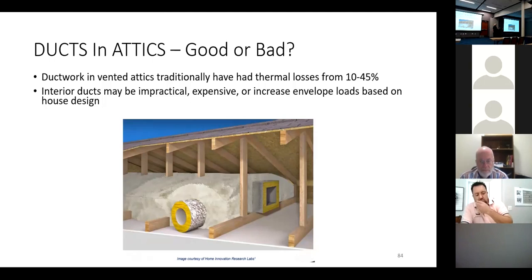So by amendment, the leakage rate right now is ridiculously high. You can leak 6 CFM per 100 square feet. So you build a 2,000 square foot house, 120 CFM. Do you want to leak that much air? I don't think so.